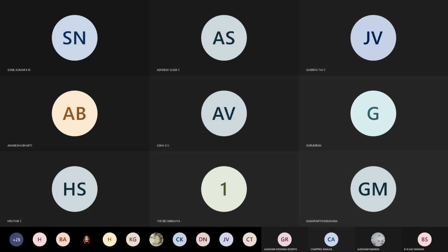The same thing we are going to make here: RA is equal to RB is equal to RC. Suppose the resistance you connect here, RA, RB as well as RC, is made equal to RF, so all the resistances are equal. Substituting in this expression, RF equal to RA gets cancelled here, this also gets cancelled, and this also gets cancelled, resulting in the output voltage expression as minus VA plus VB plus VC.